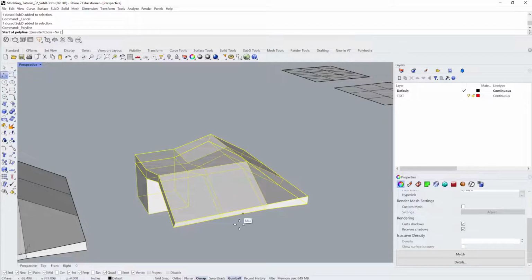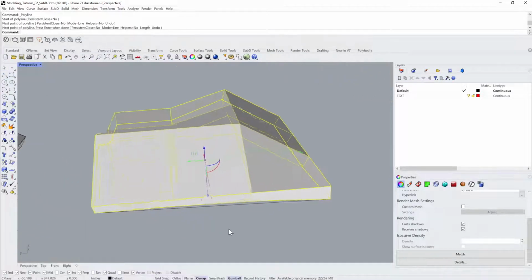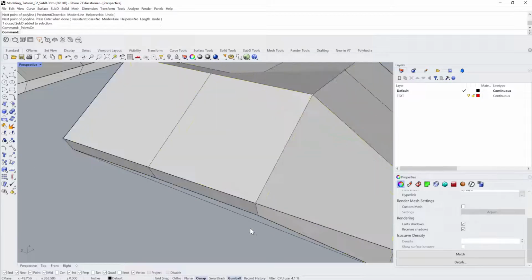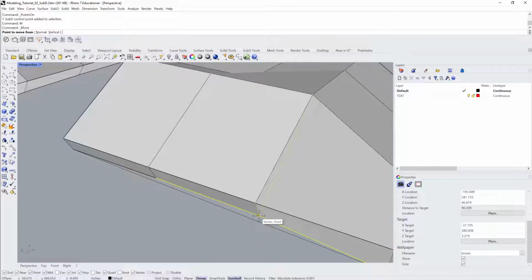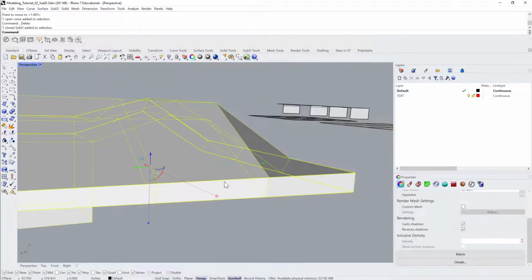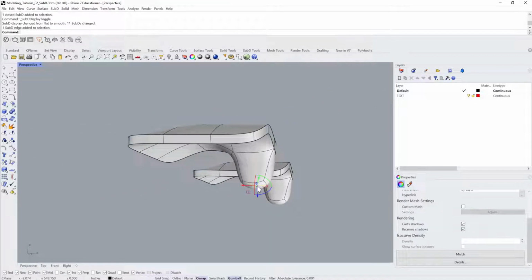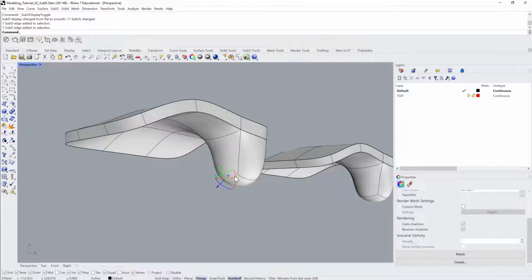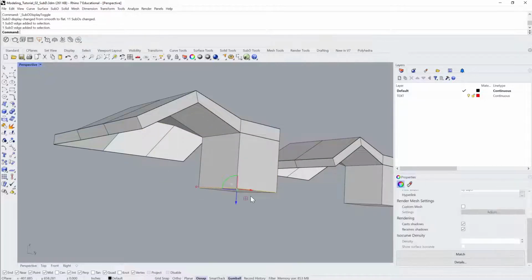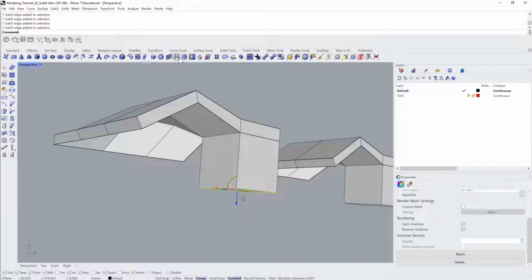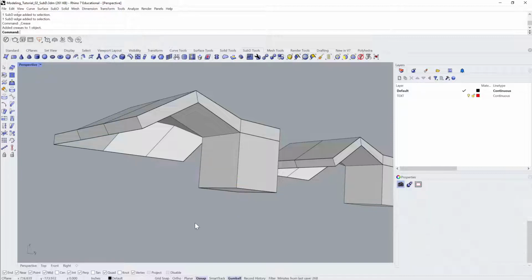And a lot of times we just push and pull vertices. So maybe I'd set up some geometry here, hit F10. I could hit Shift Control. I'm just going to use this reference geometry and snap that to this, so that I control how that is working. I've got this funny foot here, but let's say we could get rid of that by coming in and giving ourselves a crease here. So go back to SubD tools and crease that. There's the crease, like that.